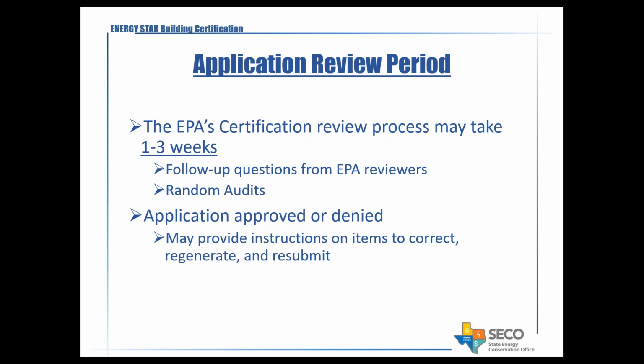So one of the things over there, the random audits, they're doing them much more frequently, it looks like. And basically what they're looking at is that all the conditions that you had indicated, for example, if they want to clarify the outside air requirements, they may be asking you to show a picture of your screen, basically, that shows the outside air dampers were open on your EMS controls, or a statement from whoever did the site verification to indicate what the conditions were.